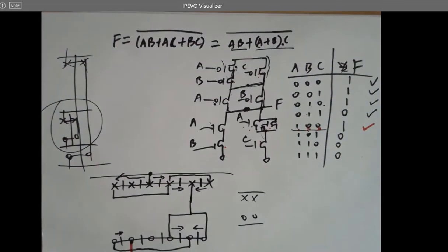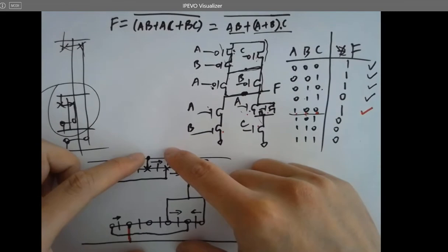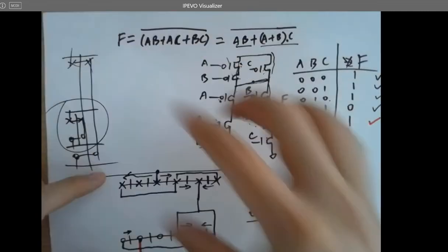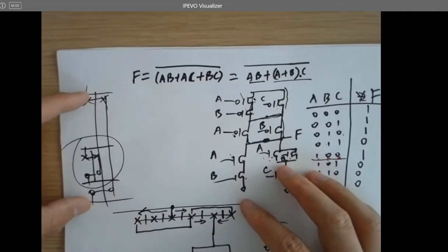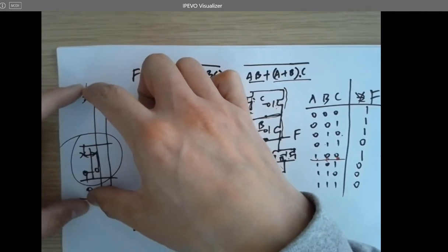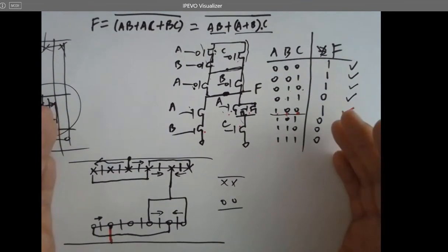There's a ruler tool in Electric VLSI. You can measure this distance. You just find the longest one of any of the blocks you have developed, measure the distance here, and then go back to the inverter's layout and expand it to exactly the same length, so you can just put it back here in the future to make one functional block.